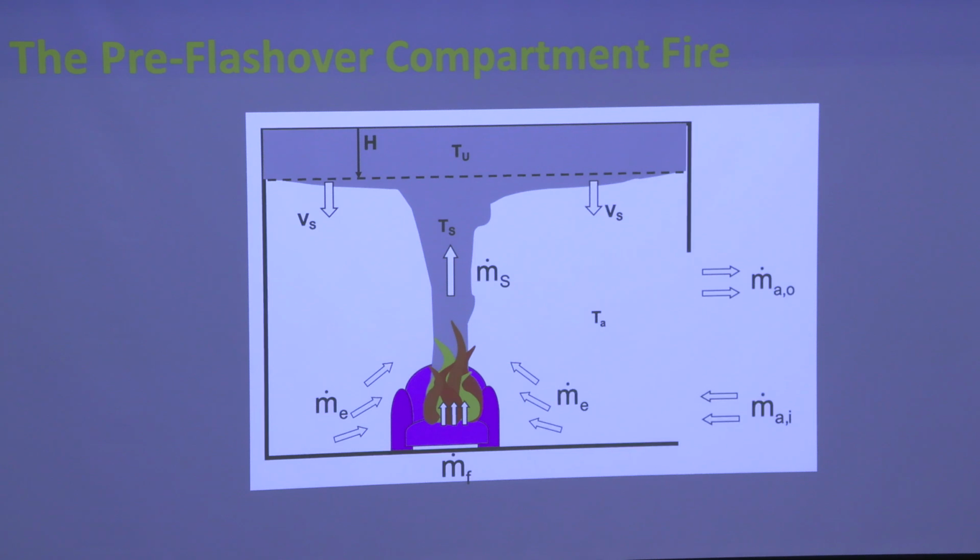Okay? Think about it. What you have is a system that is stratified. So all the momentum is going to basically be absorbed in the interior of this, basically mixing the smoke in a way that you can assume that the entire control volume is at a homogeneous temperature. So there's no longer X, Y, and Z. Effectively, there's a single temperature that represents the control volume, and you're assuming that all the momentum introduced by buoyancy is used simply to mix this and create a perfectly stirred reactor on top, okay? So what you have is effectively a perfectly mixed hot layer at a homogeneous temperature. You ignore the bottom layer because all you need is the transfer of mass.